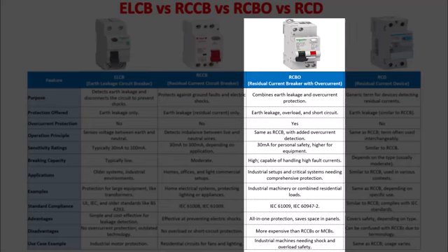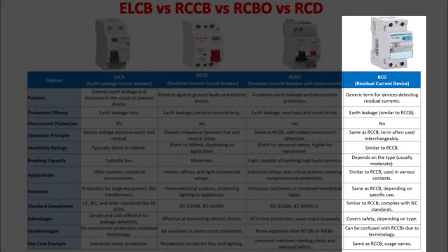Finally, the RCD, Residual Current Device, is a category that includes RCCBs and RCBOs. It's the family name for all devices that monitor leakage currents and disconnect to prevent harm.